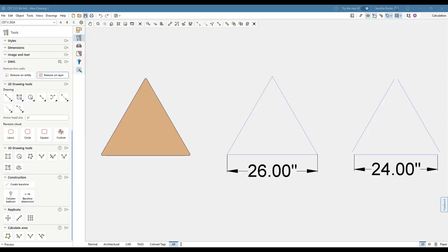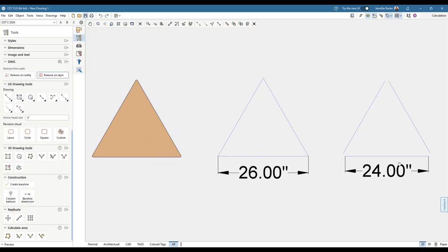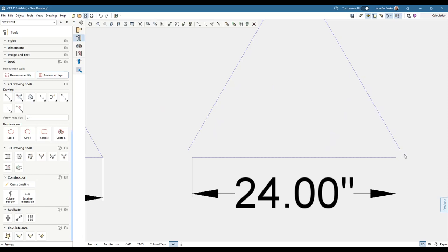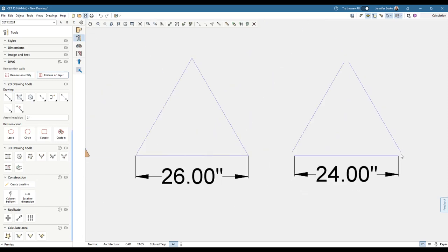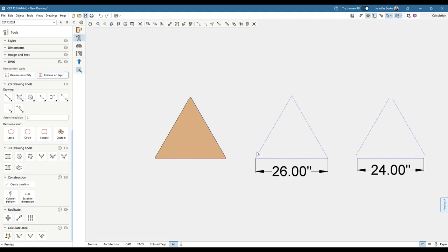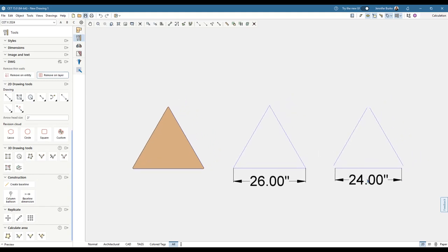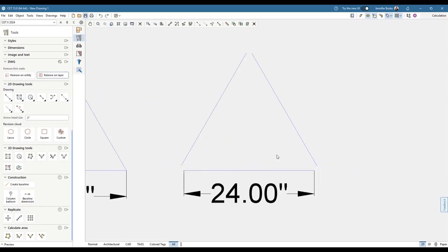What we're going to do is draw help lines that are 26 inches triangular, which is the overall size of the actual unit. We're going to cut them back to be 24 on each side, so we have that gap. What that gap is representing this time is the edge banding around the hole. So we kind of think of it like a picture frame. We still want to have a frame around that hole, and then we still want to just have that negative space of the 24 inches. So you can certainly start by drawing the 26-inch help lines, then drawing 24, and replacing the 26. That is what I did.